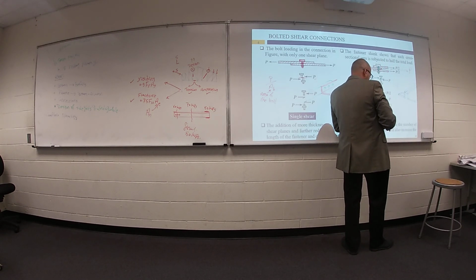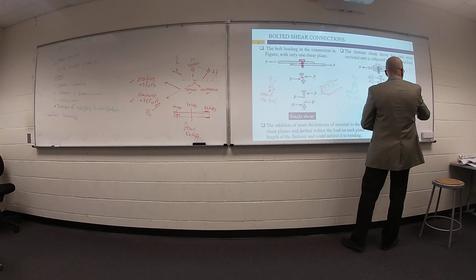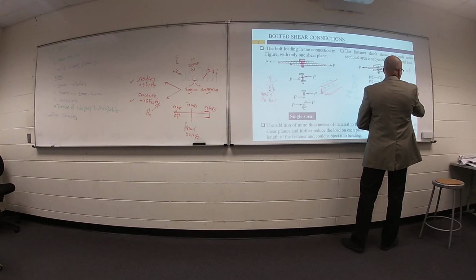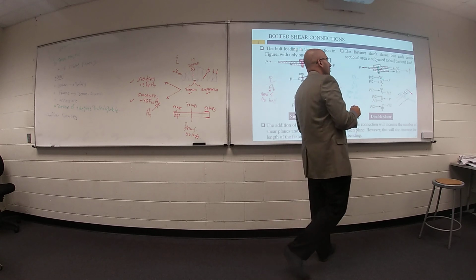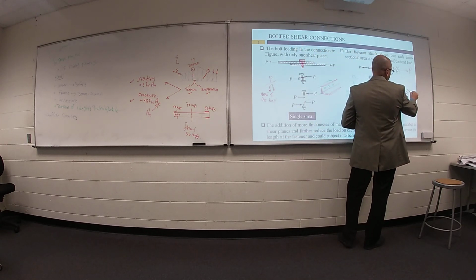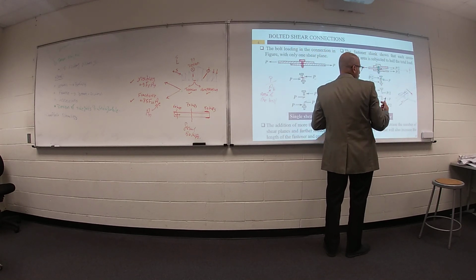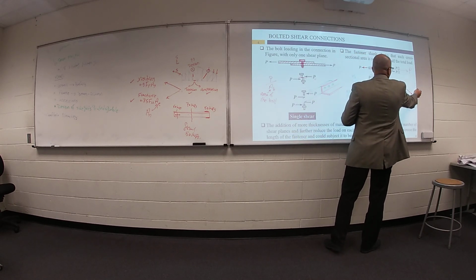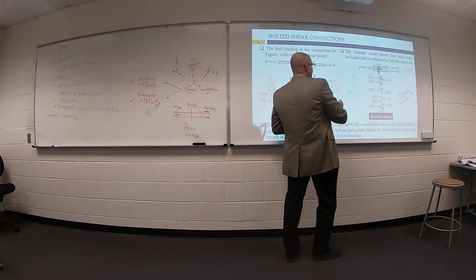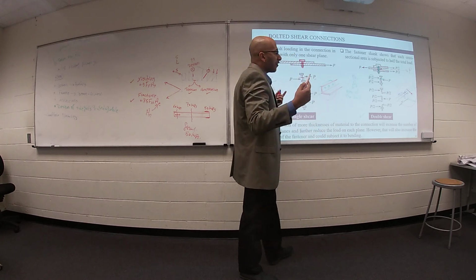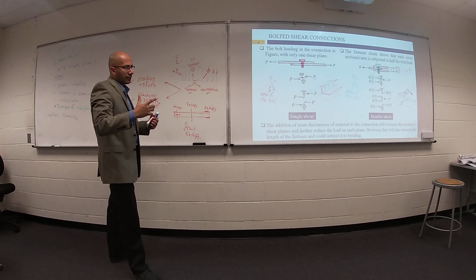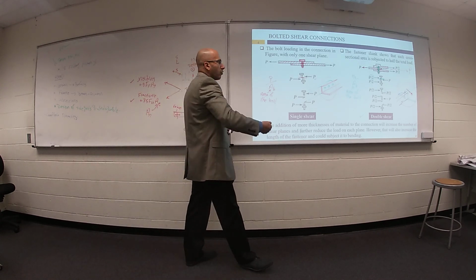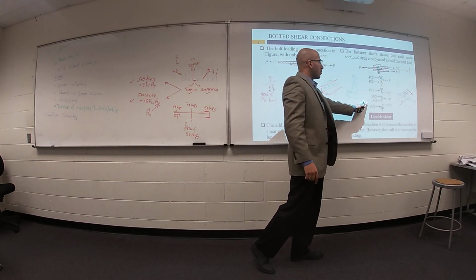And in between we have your plate, and you have bolts here. So if you have a double angle connected to a gusset plate, we have double shear. So we can expect this connection is stronger than this connection. So we prefer our members to be double angle, double channel, something like this, to improve the behavior of your connection.